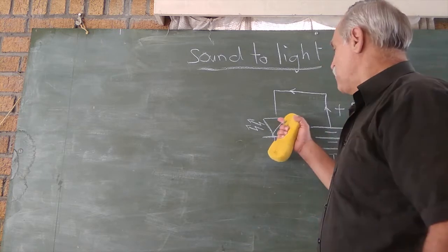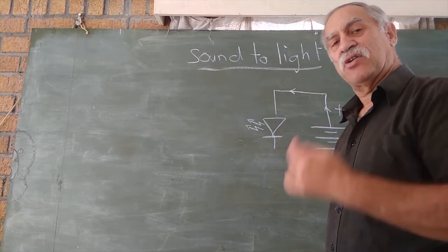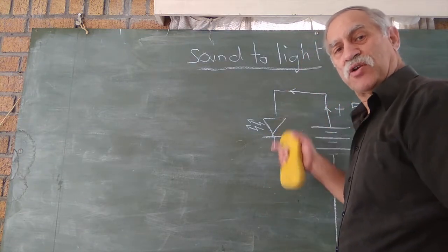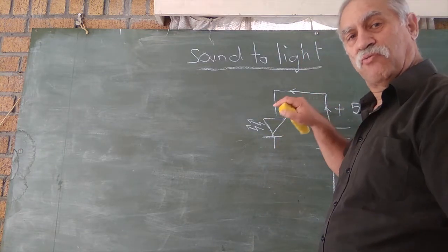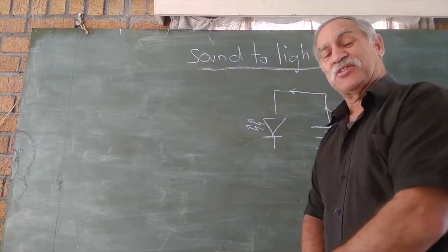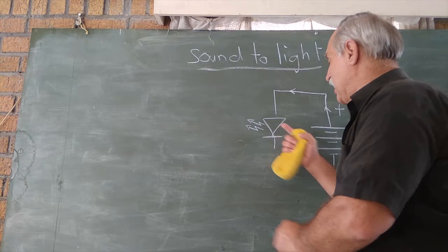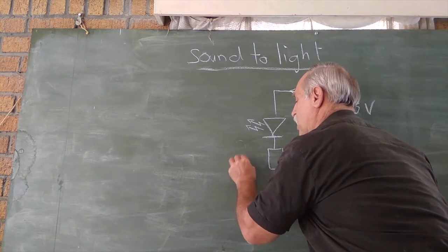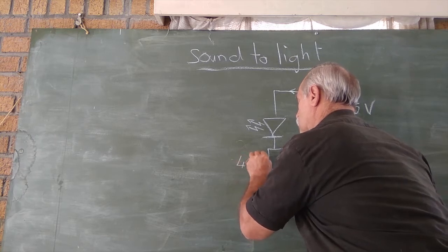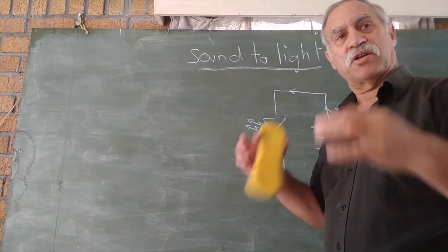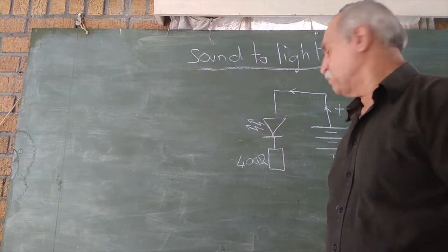But every semiconductor, like a diode or transistor, needs some protection to stop runaway current, because it either switches on or off. It's got no real resistance. What is the thing we're going to need to protect our LED? We always have a resistance of about 400 ohms. Can be 200, can be 180, but just as long as we've got a couple of 100 ohms resistor.